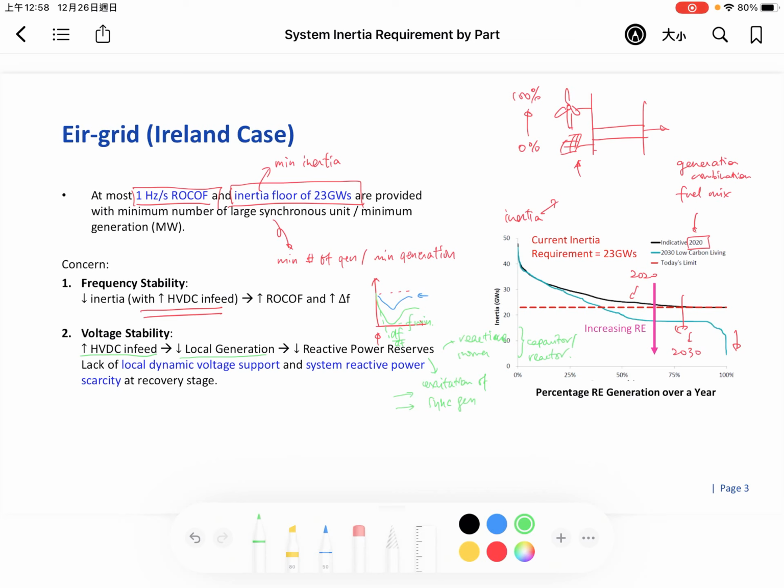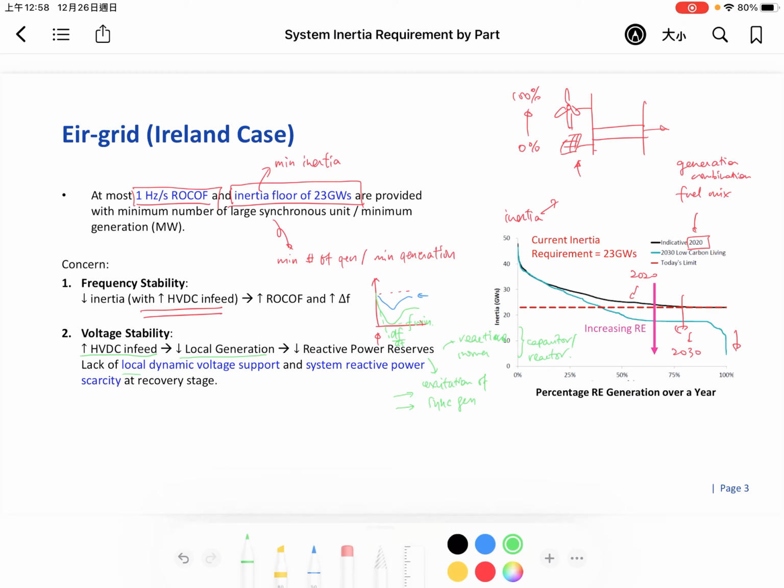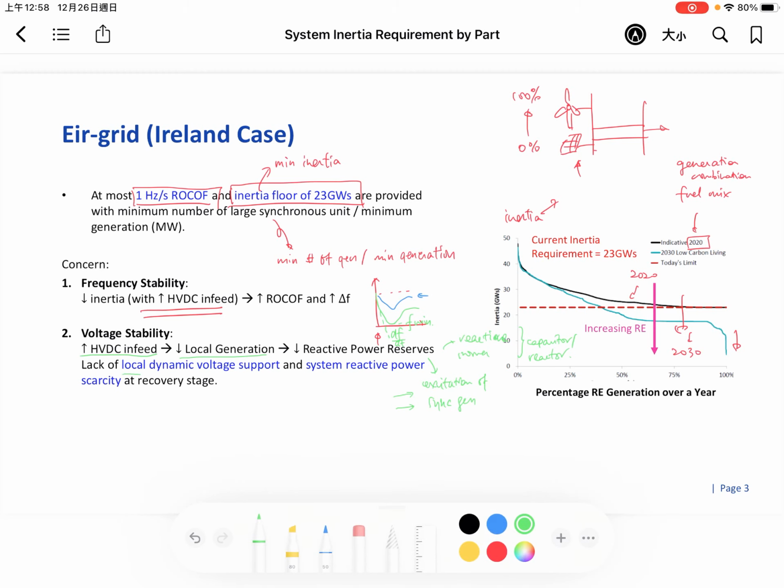Let's note that first, this is local because voltage support requires more reactive power at the local stage. Just consider a transmission network. If we want to push P plus jQ to the right, it's much more difficult to push Q because the X is much larger, and hence it's better for us to install some kind of devices to provide local support.